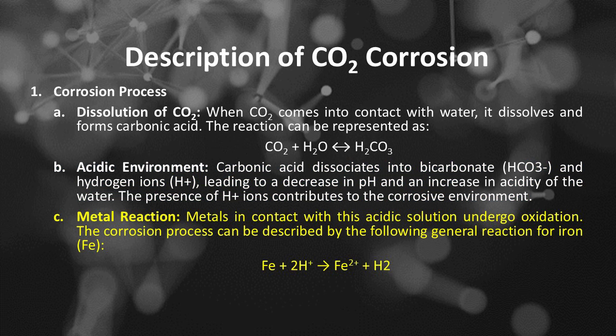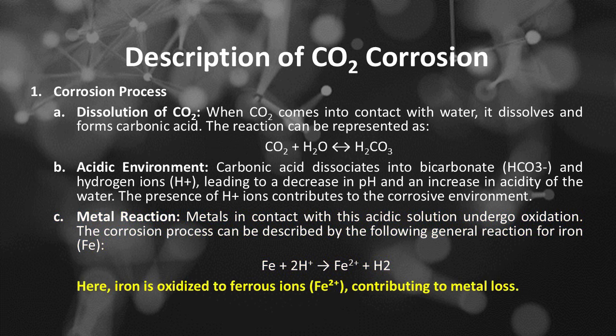C, metal reaction. Metals in contact with this acidic solution undergo oxidation. The corrosion process can be described by the following general reaction for iron, or Fe: Fe + 2H+ = Fe2+ + H2. Here, iron is oxidized to ferrous ions, or Fe2+, contributing to metal loss.